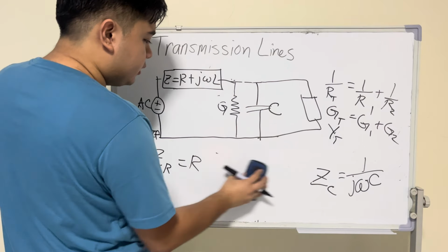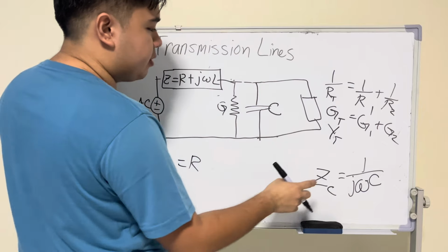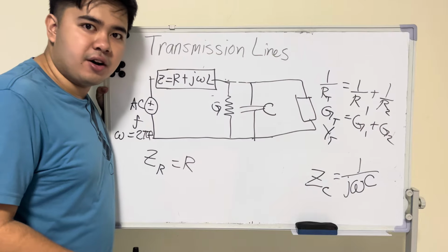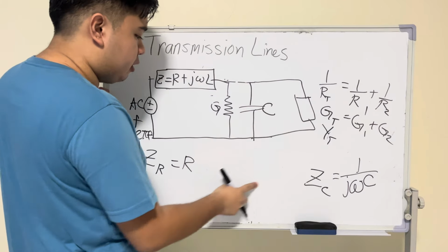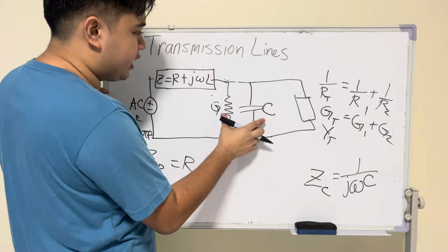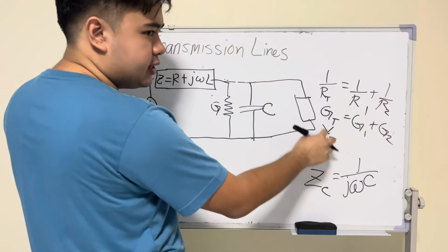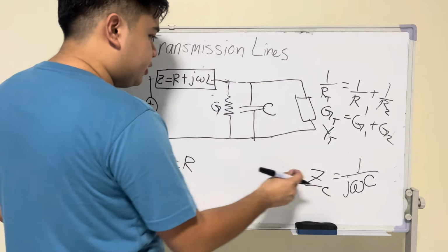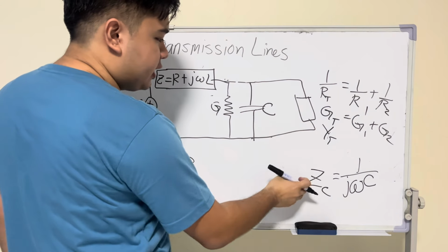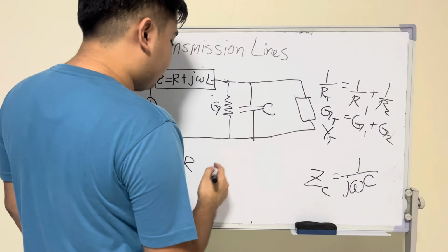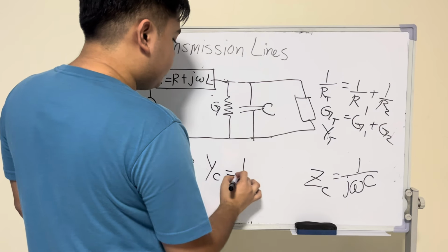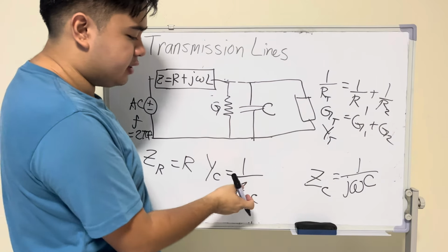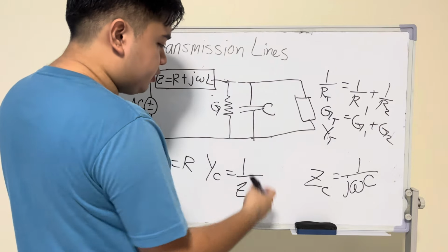Let's remove this one because we don't need inductances anymore. We do have the impedance of a capacitance here, but we need the admittance now, so we can add these together, because the admittance and the conductance have the same property in parallel here. The admittance of a capacitor is just 1 over the impedance of the capacitor, so the reciprocal, right?